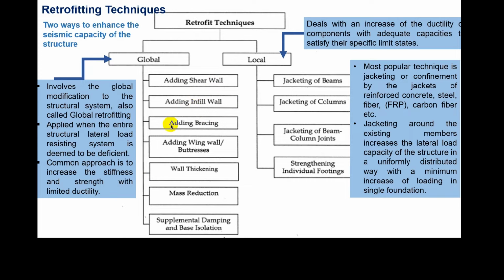Addition of shear wall, infill wall, bracing, wing wall or buttress, thickening of wall or increasing the thickness of the existing wall, mass reduction of the structure.